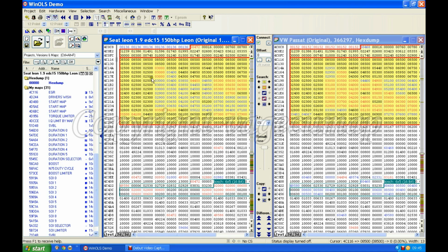And I have a sneaky suspicion that the reason is not simply because of fueling, as in, oh well, obviously this one's got more fuel than that one because it's got more power. I suspect it's more likely tied in with the fact that the injectors used on the two engines are very, very slightly different, even though people often say that they're the same. I think they are marginally different in flow rates, and the end result is that the air requirement, or the EGR flow allowed, is slightly different.